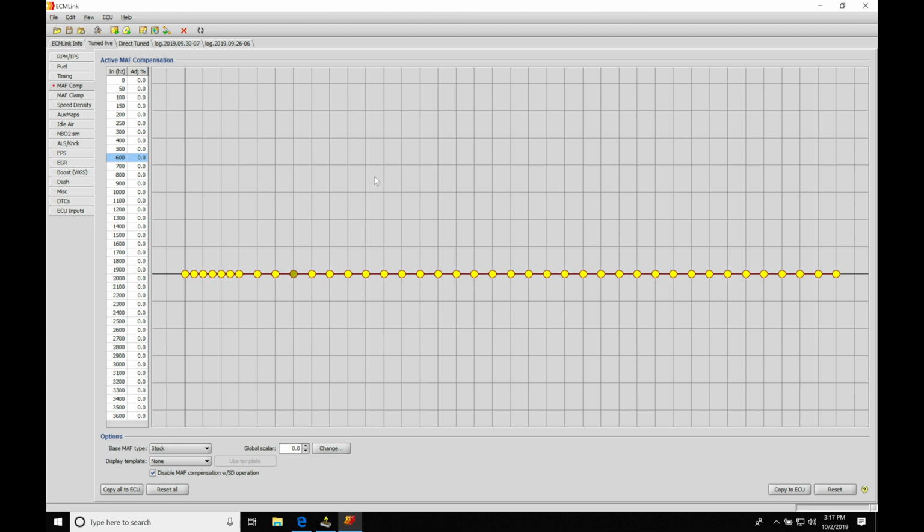So what we'll have is a primary O2 sensor. That's going to be our front O2 sensor in the O2 sensor housing. That is going to be a narrow band sensor. The narrow band sensor is going to be a 0 to 1 volt scale, and around the half volt point, that's going to be the output that's equivalent to 14.7 to 1. So when it's reporting back the air fuel to the ECU, the ECU is going to be taking a look at that voltage range. If it sees a half volt, it knows that it's at 14.7 to 1. If it's going to be higher or lower than that value in voltage, it's either going to be leaner or richer. So we're going to have to start to make some adjustments, and that's what the short and long-term fuel trims are going to be doing.